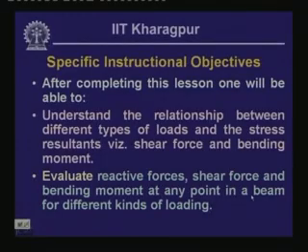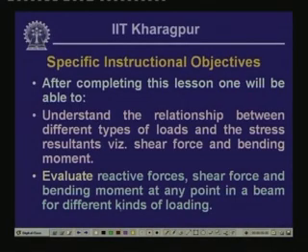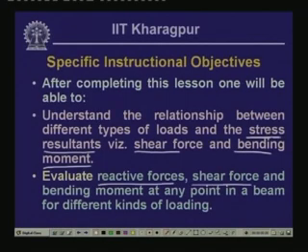Once this lesson is completed, one should be able to understand the relationship between different types of loads and the stress resultants, which are shear force and bending moment. If you remember, last time we introduced and discussed the aspects of shear force and bending moment, and these quantities we call stress resultants. Also, one should be able to evaluate reactive forces, the shear force and bending moment at any point in the beam for different kinds of loading, or at any section along the length of the beam.